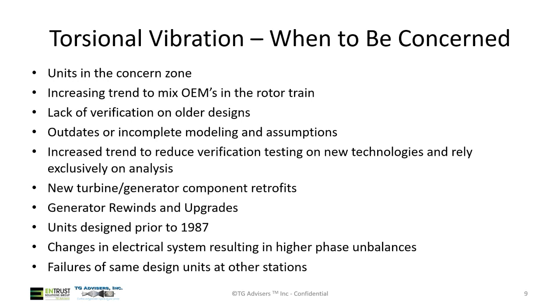Sometimes your modeling or assumptions were done many years ago, and they may need to be revisited depending on when the analysis was completed. There's also an increasing trend in the industry on new technologies to rely exclusively on analysis. Remember too that sometimes you do need to do the verification testing, and in torsional that would be a torsional test when you bring the retrofit online if you're in a certain frequency zone.